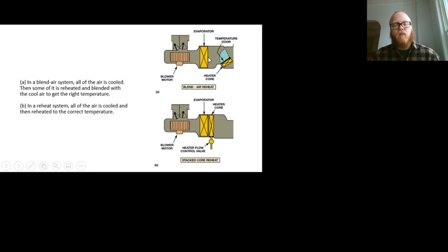This is on full, as cold as it gets, somewhere around 32, so that the water on it is just about to freeze but not quite frozen yet. Air passes through it, bypasses the heater core, but there's still this hot spot inside the plenum which heats up some of the air as it goes by. In this case, if we can shut it off so that this never comes up to temperature and we have our nice cold air coming through our evaporator, well, then it's going to be as cold as possible inside the vehicle. So just two different takes on a similar concept.